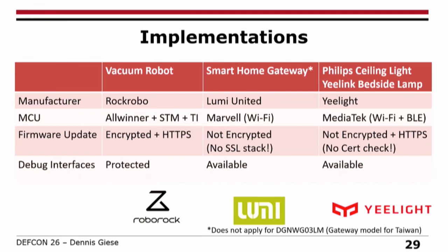Another case is Yeelink, where they have some lighting products where they use the MediaTek chip. And here the firmware is also not encrypted, but they use HTTPS. The thing is they don't check the certificate, so you can just give it any certificate. And the fun fact here is they actually have root CAs in their firmware, but they don't check against them.